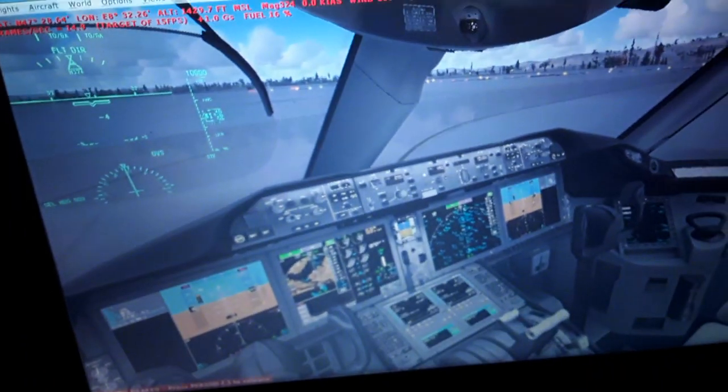So we have also the ILS localizer. You will see the horizontal localizer and the vertical glide slope, which will align us with the runway heading, and also the angle of approach, the glide slope. We have the ILS crossbars displayed in the primary flight display. We have the flight director crossbars for manual guidance of the aircraft, and the autopilot crossbars for automatic guidance of the aircraft. We have the angle of attack of the aircraft as it flies in the flight mode, balanced here with the autopilot and the autothrottle.